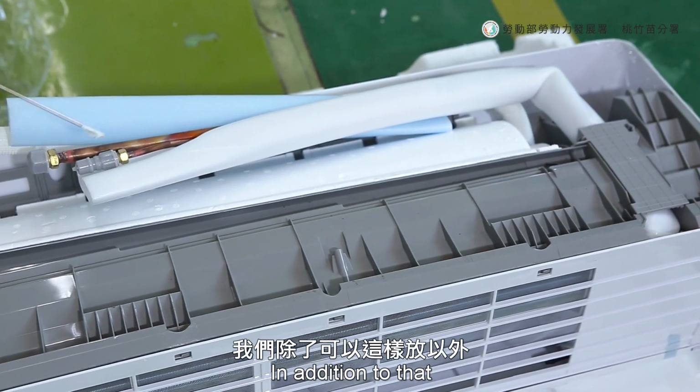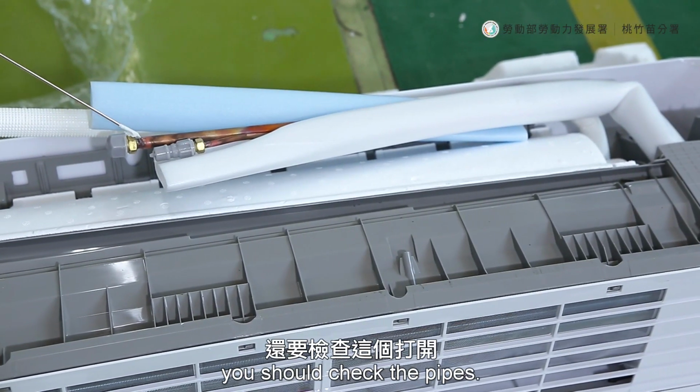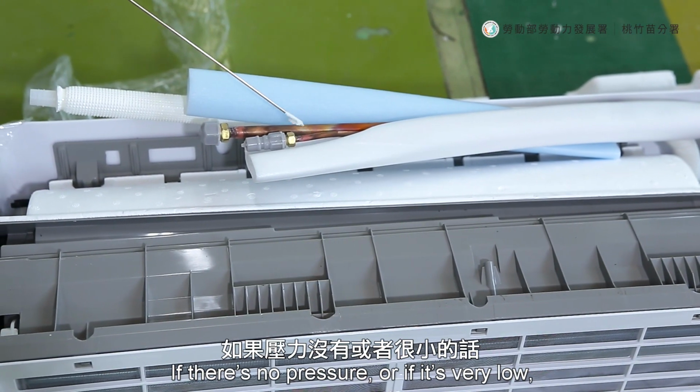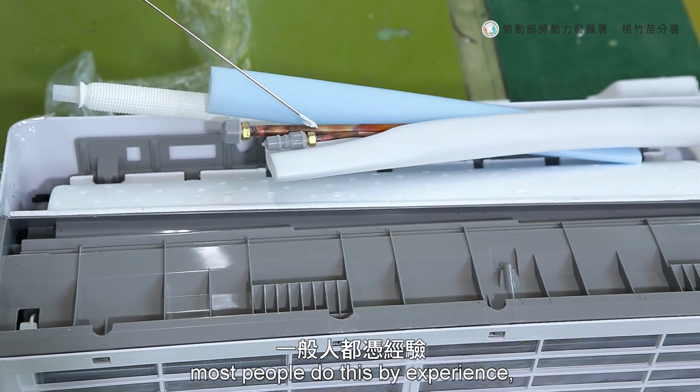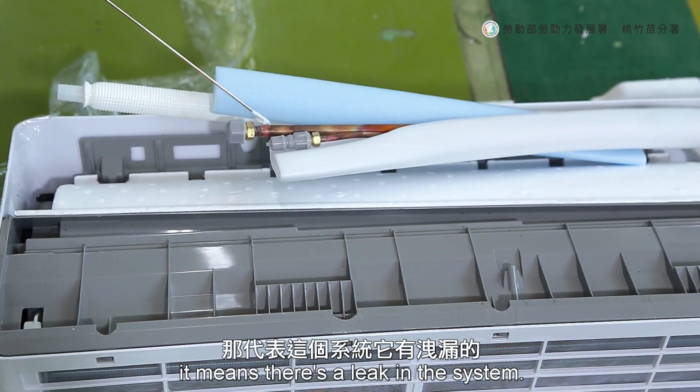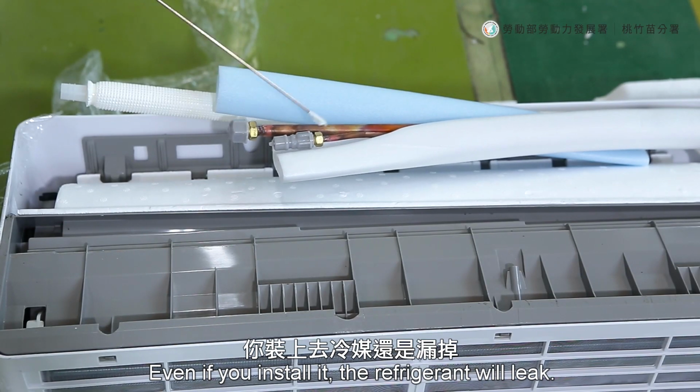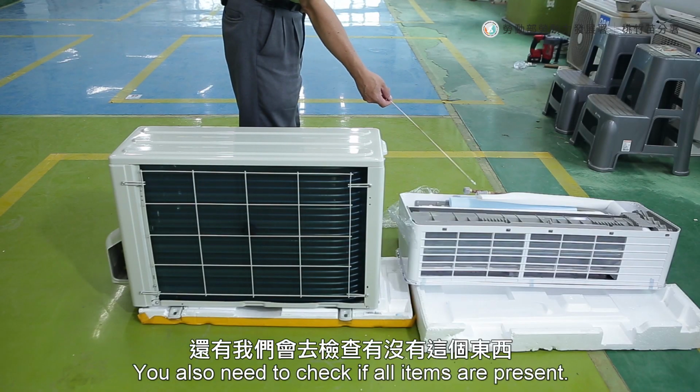In addition to that, you should check the pipes to see if there's pressure. If there's no pressure or if it's very low, most people do this by experience, it means there's a leak in the system. In that case, don't install it. Even if you installed it, the refrigerant will leak. You also need to check if all items are present.